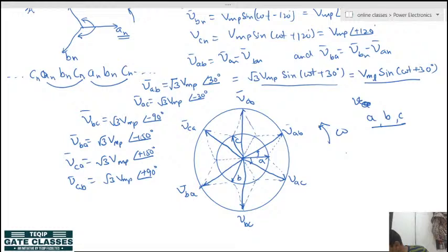All right. So we have to remember this ABC. If phase sequence is ABC, then line sequence is this. You don't have to cram it, you just remember what the phasor diagram is. From that you can just derive it. So we have got AB, AC, BC, BA, CA, and CB. But this is true only if the phase sequence is ABC.